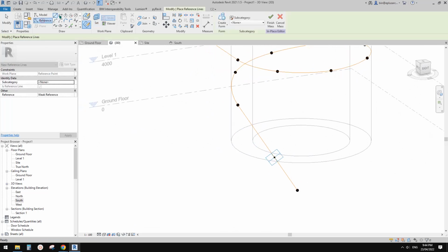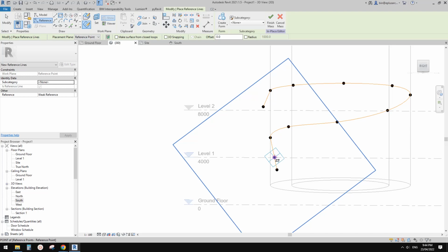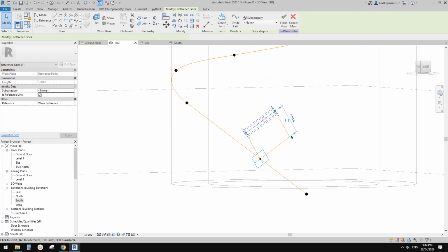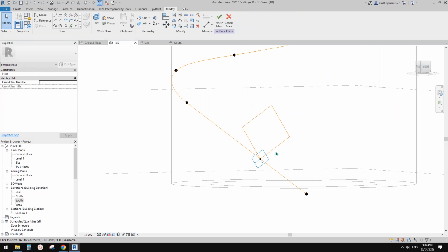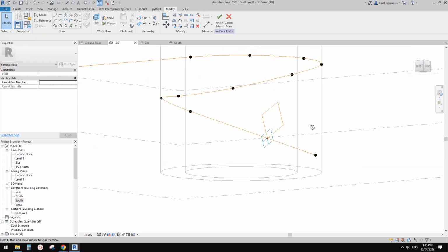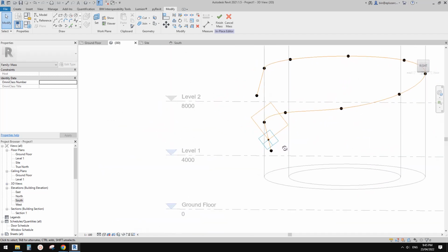we can start to place a profile onto this work plane of this point. So we're going to use rectangle, draw on work plane, set to work plane, pick this work plane, and I'll just roughly draw it. Okay, maybe let's make it 1800 and maybe 2100. So 1800 wide, 2100 high. So, and there's an angle, so that's fine.